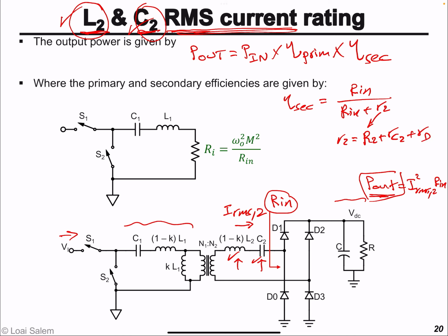So we know that when a diode conducts, essentially it can be represented as a resistor, small r_d, and there is a forward voltage drop, for example, like in this way, Vd, where this is the anode terminal and this is the cathode terminal of the diode.